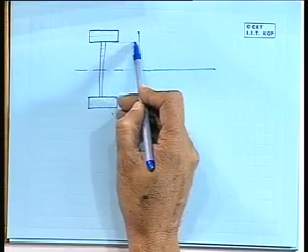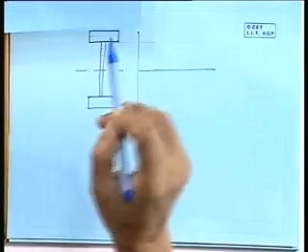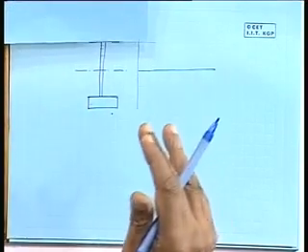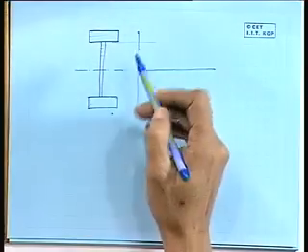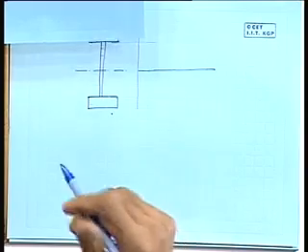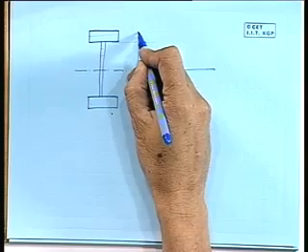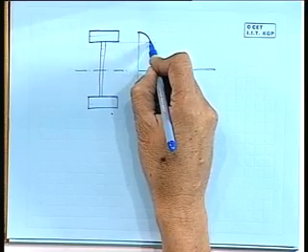and it will increase parabolically, because what is y b dx dy integration. Now, dy is dy, so that integration will give you a y square by 2 term, y into b into dy integral from y to ym will give you y square something. So y square means it is a quadratic in y, okay. So quadratic in y will give you a parabolic distribution. So from here to here this will be a parabola going like this.